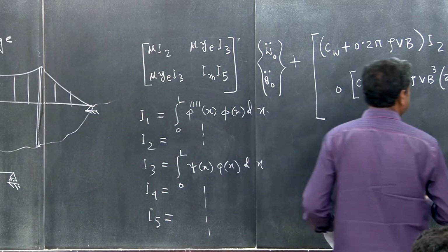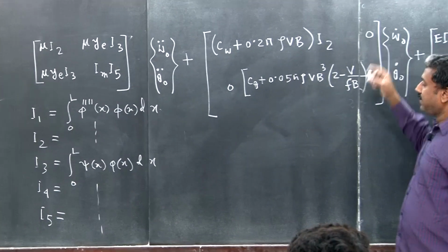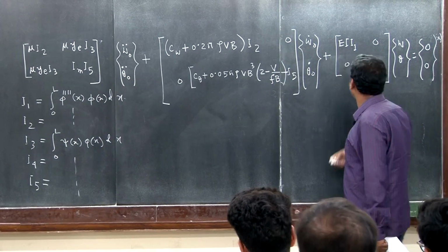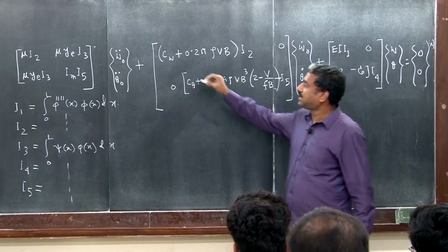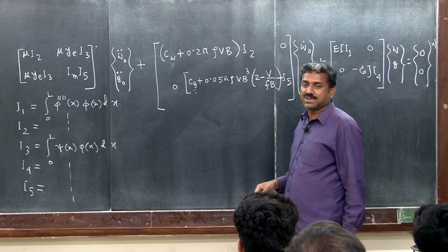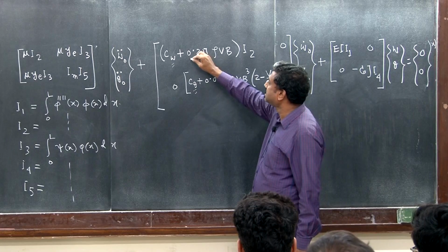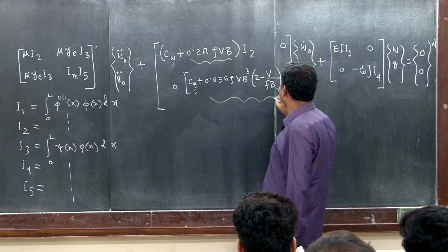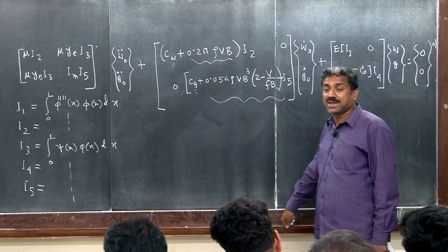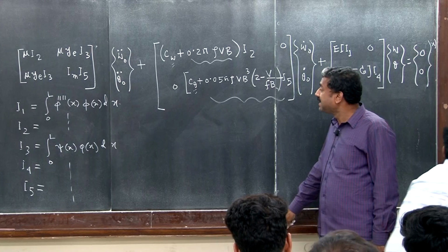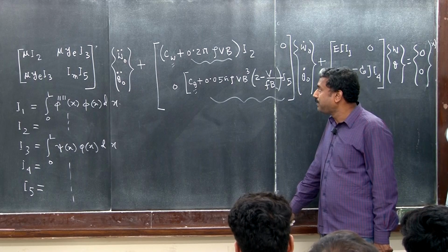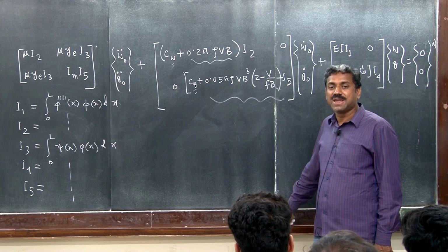So what we can clearly see here is that the aerodynamic loading essentially got incorporated into the damping term. Right hand side is a homogeneous system of equation. So these were damping from material terms, right? This damping is viscous damping. But additionally, because of this aerodynamics, the force that is being exerted on the deck by the fluid structure interaction is expressed in terms of the response of the structure, right? So it is the damping that is coming. So effectively they are contributing in damping.